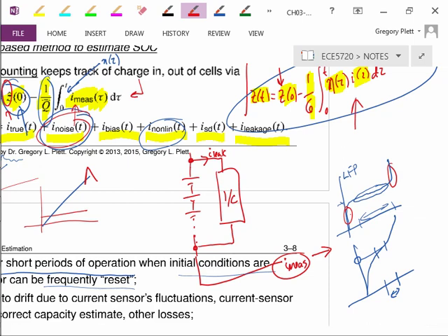So that's kind of a band-aid solution. I don't care for it myself, but I know that that is implemented in some real battery management systems. One of the issues is I don't get any feedback at all until I'm almost at the very edge of operation, and that is a big concern because my SOC estimate might have been significantly wrong, thinking that I had lots of power available, and then I get an accurate update that says, oops, make a huge adjustment right now to say that there's no power available, and that would be very, very bad in application.